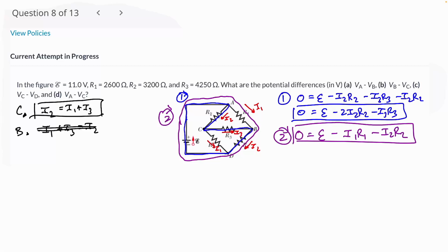You want me to do the system? Do it in red. So we've got to rewrite these equations in a way that the linear solver is going to work. So I2 minus I1 minus I3 equals 0. And so that's minus 1 I1 plus 1 I2 minus 1 I3 equals 0. So I'm looking for the coefficients in front of my unknown values here.